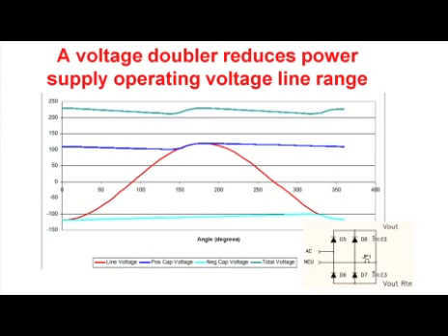The only downside to this connection is if the jumper gets installed in a 220 volt application, and now you may make 600 volt rectified voltage for your power supply, and it may create some problems for your power supply.